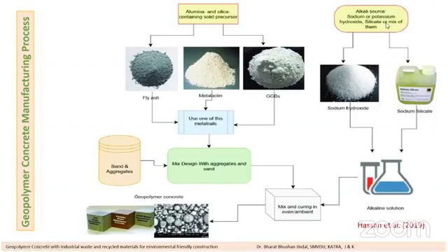And after that, here we are creating alkaline solution, sodium hydroxide and sodium silicate. We are adding them as per requirement, as per the mix design methodology. And when you add them, you will get an alkaline solution. And that alkaline solution is added to the dry material, that means sand, aggregate as well as fly ash. After that, you are getting geopolymer based material. It may be geopolymer mortar, geopolymer paste, or geopolymer concrete.